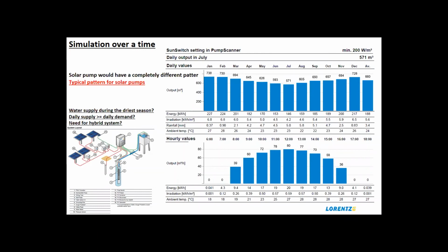So you need at least to do 2 patterns, one which reflects the situation during the summertime. This is because you have more water during the summertime, more pumping intensity, and you need to check your system in terms of size of piping. So with a lot of water, how will my reservoir react? How will the pipes react? How will be the speed in the pipes?